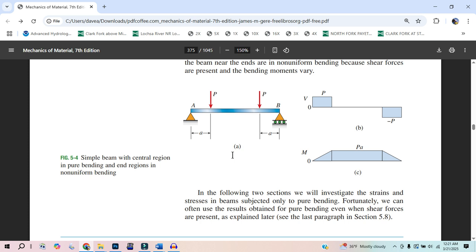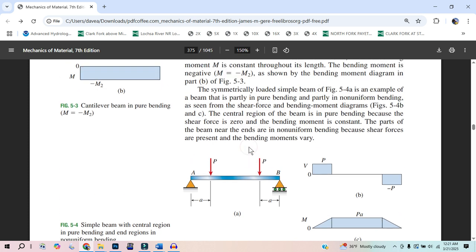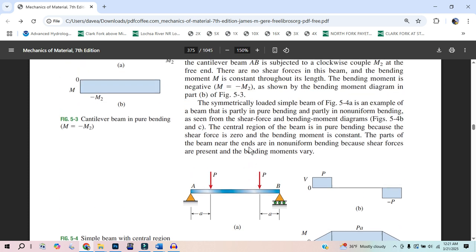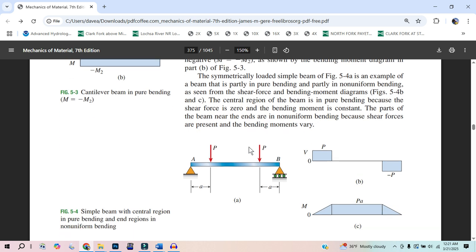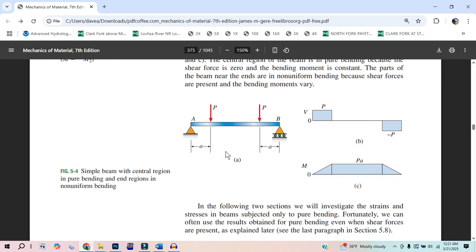That's going to be a negative 58,000 pounds. That's what we call compression. Or a tension, a positive 58,000 pounds. All right, booyah. That is a huge take-home point: even though we are having shear, this shear doesn't cause any deformation, and it doesn't even drive the strength.